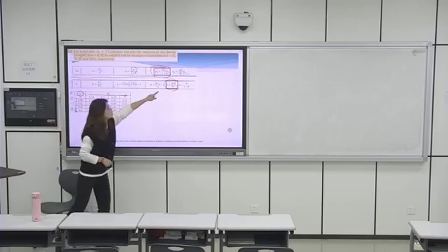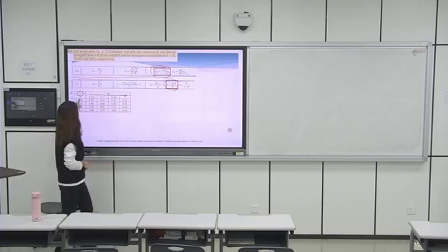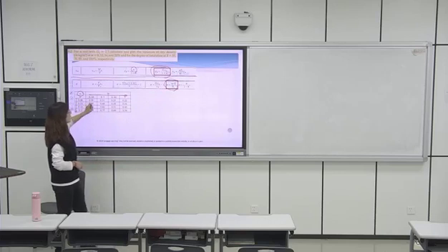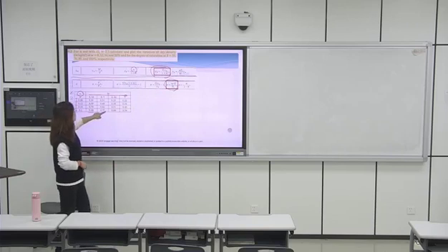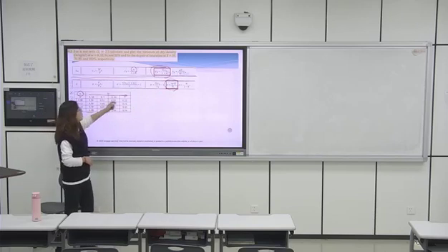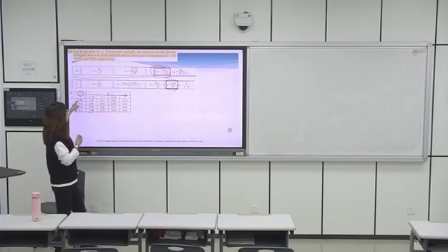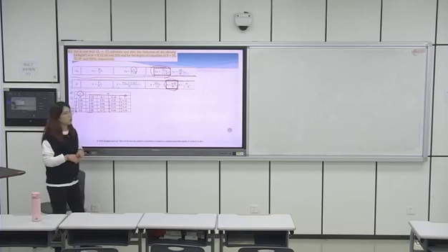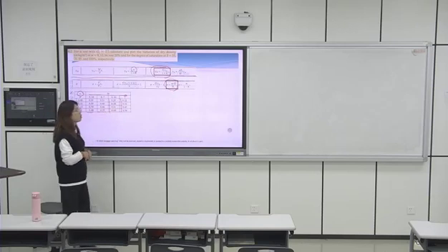We can use this to calculate it, because water content you know, saturation degree you know, and Gs you know is 2.7. Then you can calculate the void ratio. With the same one under another saturation degree for those 4 water contents, you can calculate 4 different void ratios. For the third saturation degree, again 4 different void ratios, and again 4 different void ratios under saturation degree of 1.